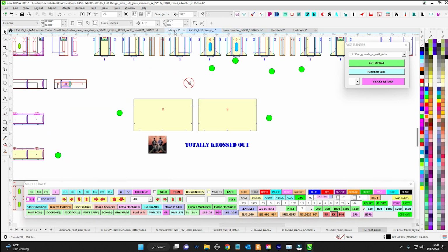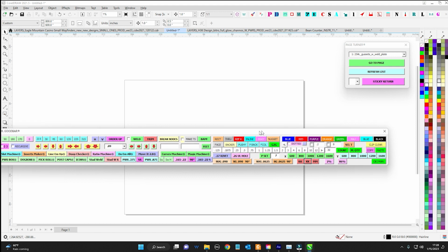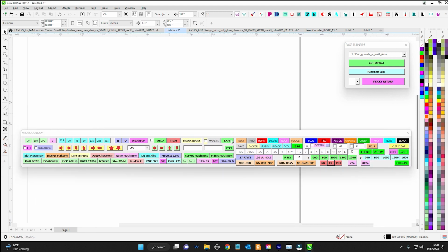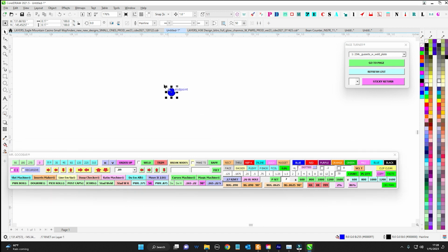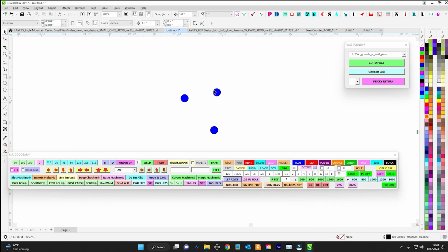So moving on, these buttons here are for creating things. As we're riveting things, this is my rivet hole. I have a dedicated circle. This circle right here is 0.17. We use 5/32 rivets. And when it's time to rivet things together, I just push a button. There's my rivet hole. Now, you can create this, but this is also named. So not only does it create a circle, it fills it with the color that I want, and it names it. So boom, there you go.